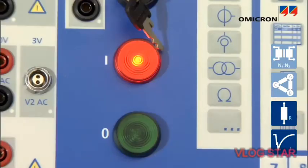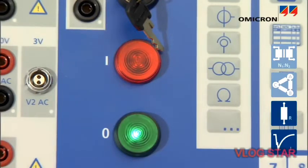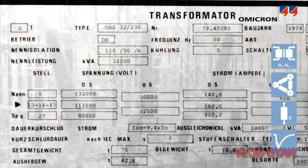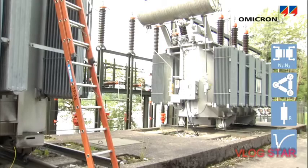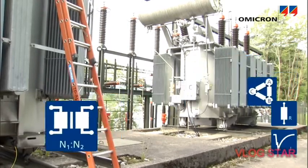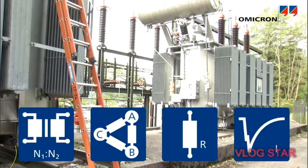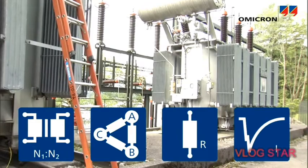At the end of the last measurement, the CPC indicates that the test is finished and that it's safe to remove the test connections. Results are presented numerically and graphically in the report and can conveniently be compared to factory results, previous measurements, or transformers of the same type. Measuring ratio, magnetization current, and static and dynamic winding resistance is faster, safer, and easier with the CP-SB1 switchbox.